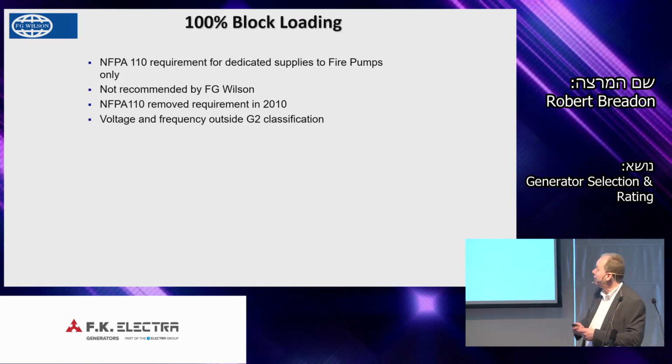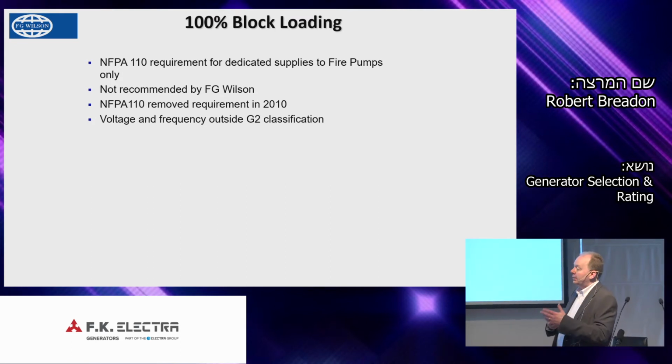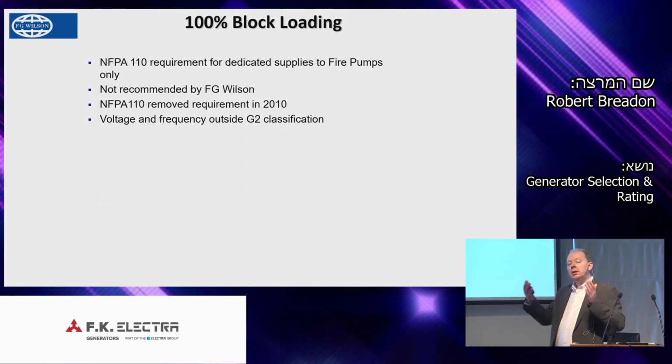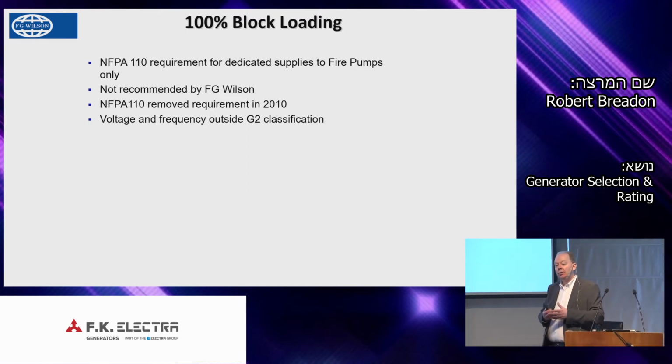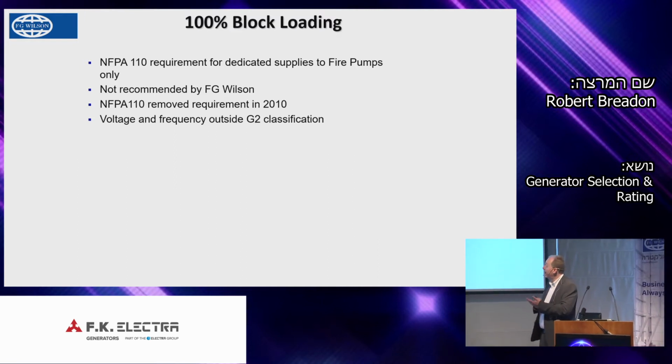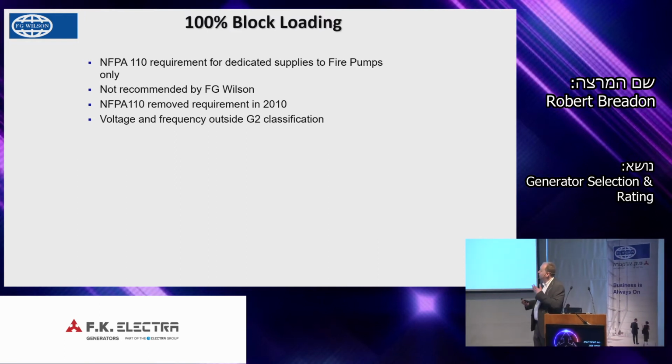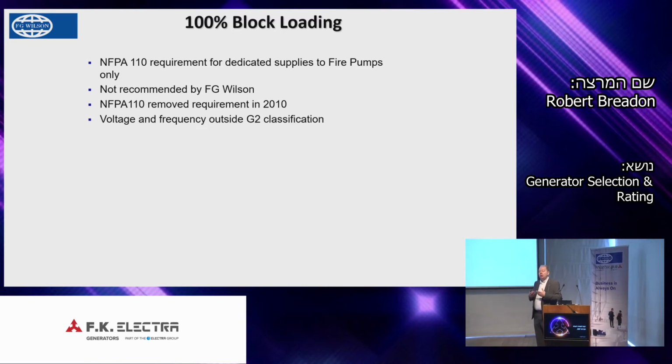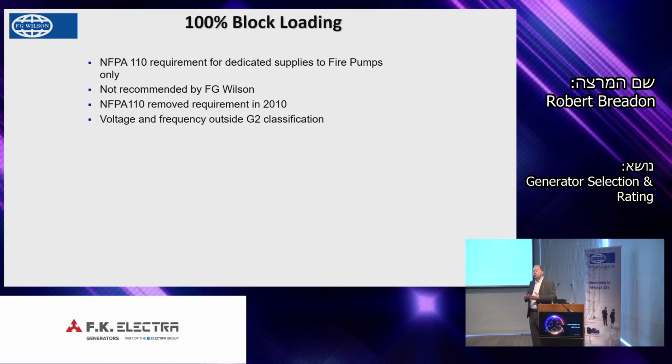NFPA, which Johnny referred to earlier, is a standard that has been in the industry for gensets for a long time, especially NFPA 110. The way they used to look at this was that the machine had to accept 100% load and not fall over. There was no voltage or frequency classification. 100% of the rated genset load was put on the machine, and the key thing was the genset had to continue to operate, so the frequency and voltage would eventually return.